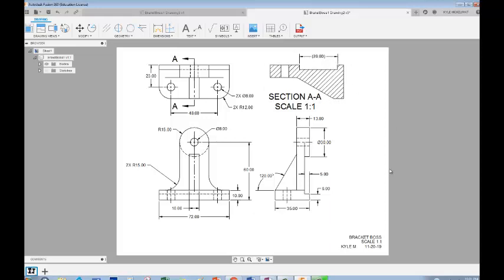Just go ahead and look over the drawing, make sure we got everything squared away. I guess this could be a little closer here. And it's kind of the draftsman's personal style, how you want all the dimensions to look, just so long as dimensions are not crossing lines or on top of your view. And everything there looks pretty good. It's a fully dimensioned part. And we've got our section view the way we need it. We've got our reference dimension. And then we've got the information in the corner that was required without the large title block that really wasn't needed.